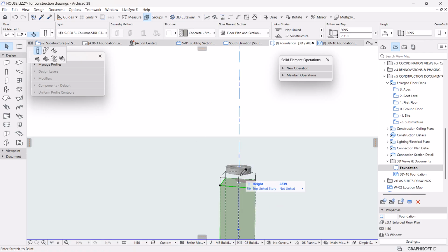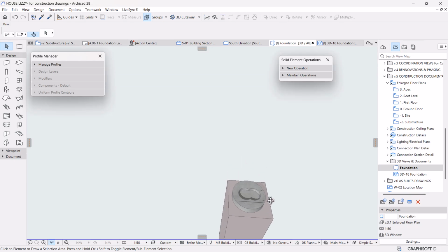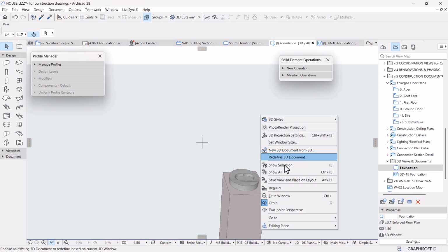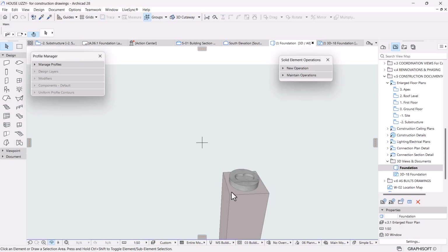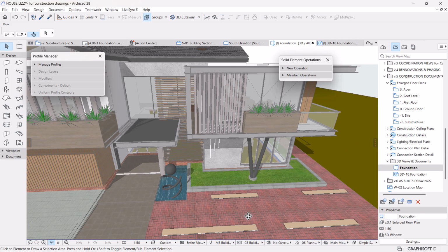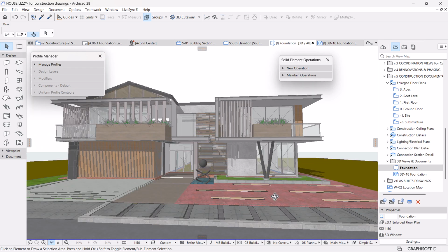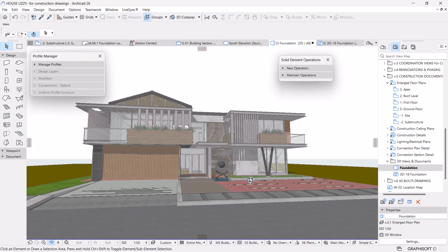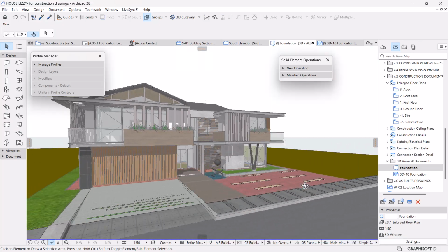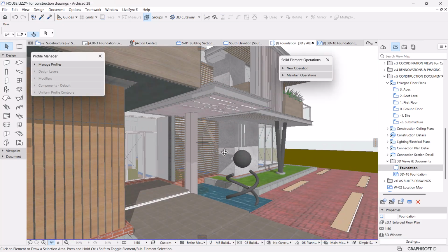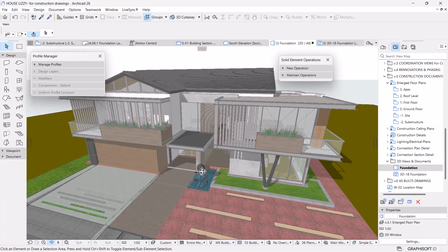Something like this. If it's possible, I would want to have it like that, so that the square base becomes hidden on the ground. So it's the detail that I need to provide the engineer with, so as to clarify even this column as well, because I don't think the foundation, the footing here, captured it well.